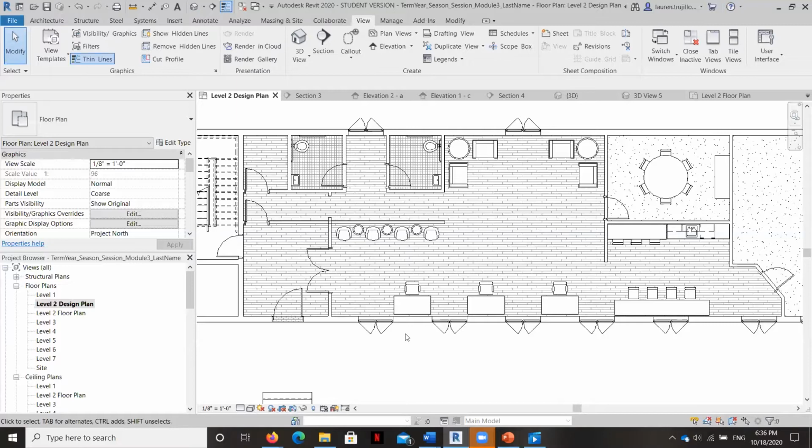So, the thing about Revit, though, is that it thinks about millwork, especially in terms of baseboards and crown molding, as sweeps. So, we're going to be creating our sweeps now. And as I said, we're going to create crown molding and baseboards because these are the two pieces that really connect or cover up any imperfections where two materials meet. And you may not know this, or maybe you do, but that's why we use them.